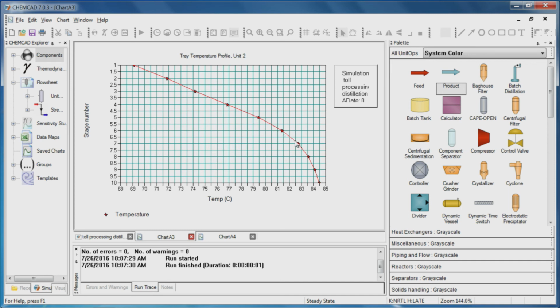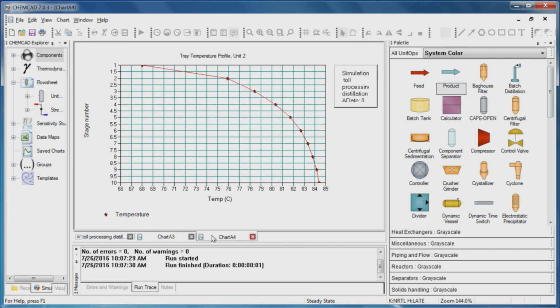And you can see that we're pretty close to not being able to meet the spec with this particular reflux ratio, because there are big changes in the column. We really need a straighter profile than we've got here, and when we use the other thermodynamic model, it's worse.